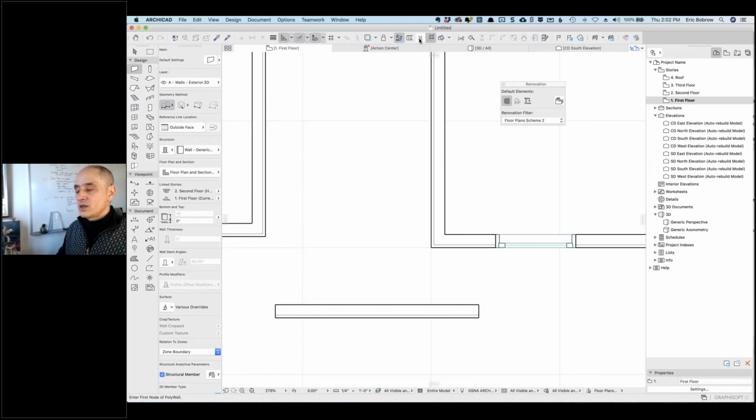So this little icon here, which also has a keyboard shortcut of Shift Option or Shift Alt, allows me to say I would like to put a measurement origin here, and then I can say I'd like to snap to the snap grid. Now, the snap grid, remember I set it earlier to the 8 inches. Well, now it's set to start at this point.